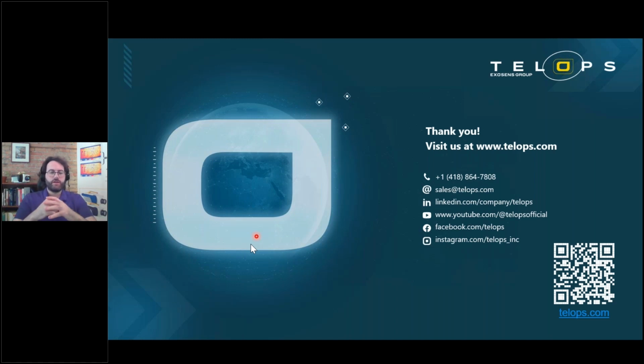So if you have an aluminum sample, you're looking at the camera, it's heating up, with your camera, you're seeing 60 degrees Celsius. Emissivity is quite low, 0.2, 0.3. You can actually input the emissivity properties in the Telops software to have a rough idea at first. And that will increase the temperature by a factor corresponding to the emissivity percentage. So we'll increase the temperature by, in this case, a factor of maybe 3 approximately.